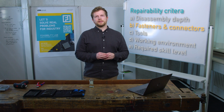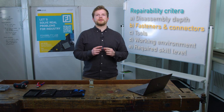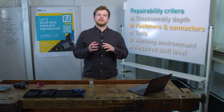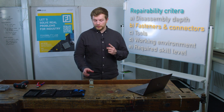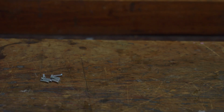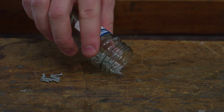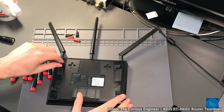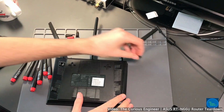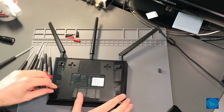Of course, it also makes repair easier to reduce the total number of fasteners. This decreases the necessary steps for disassembly and therefore also decreases disassembly depth. 10 screws are still bearable, but 50 screws in one small device can be annoying. And finally, a higher visibility of connections helps. Instead of hiding screws under caps, tape or in deep holes, make them more obvious.